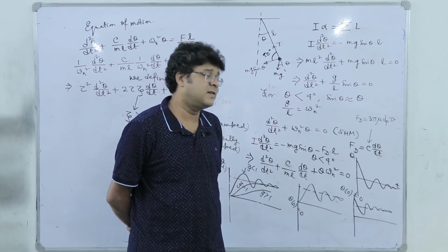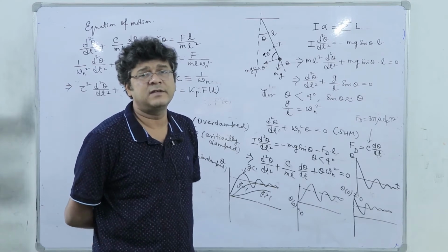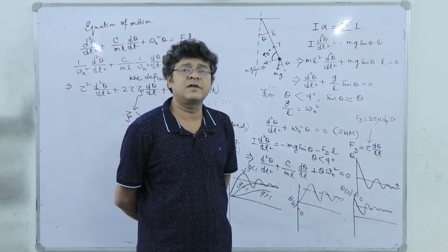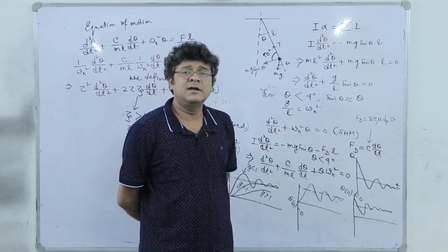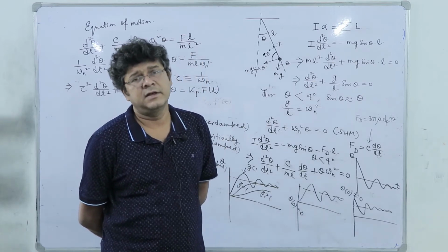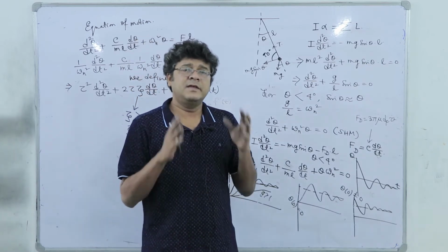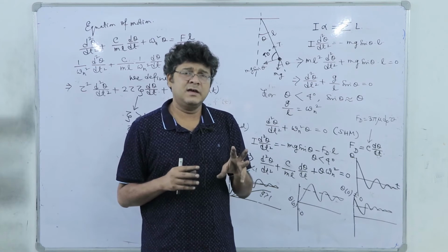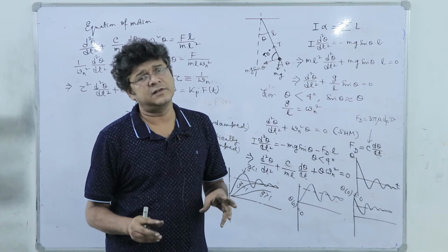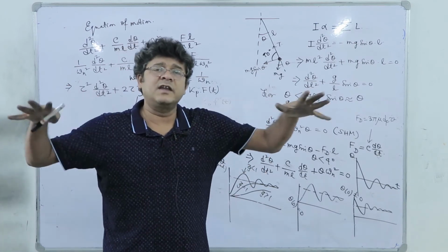where previously we saw a mercury in glass thermometer can be perceived as a second order system and also as a first order system. When will it be considered as a first order system? Where we neglect the capacitance of glass and thermal resistance of mercury, right. But if we now consider them, then mercury has both resistance and capacitance, and glass also has resistance and capacitance. So, these two are individually first order systems which are connected in series.